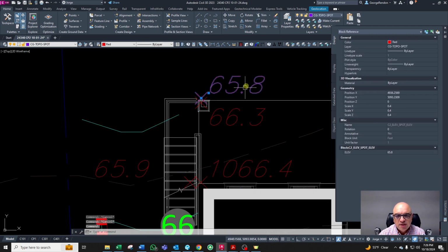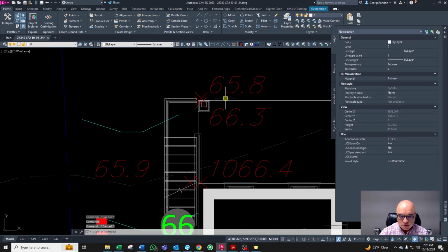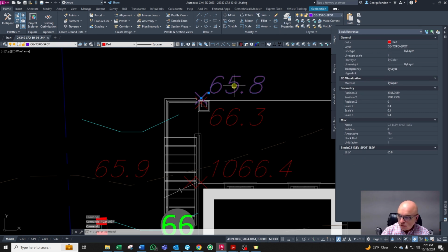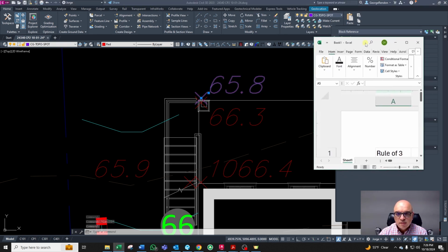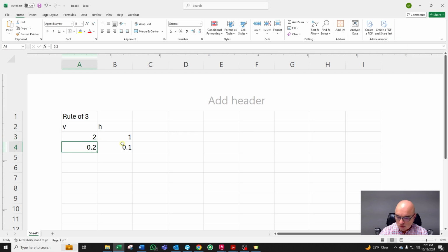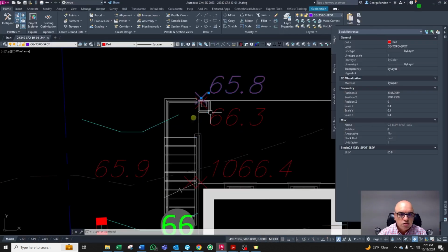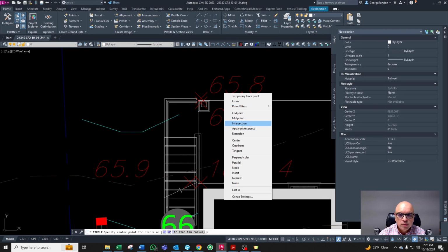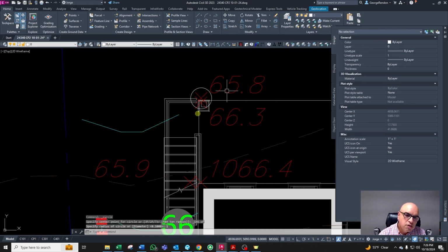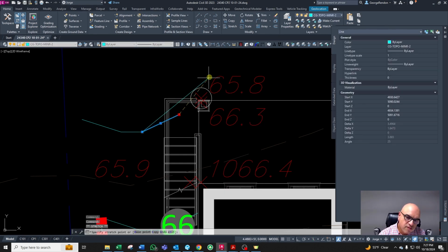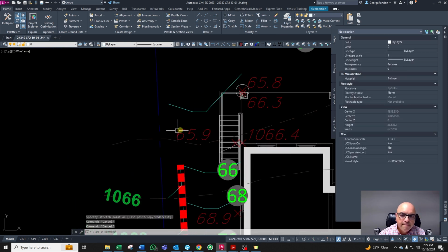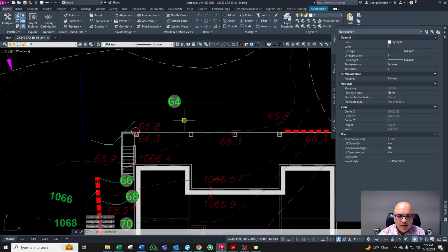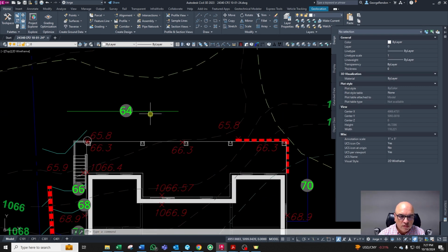But then we can be 2 to 1 on this corner. So we're talking about 1.8 feet to be at 64. So 1.8 at 2 to 1 is going to be 0.1. So we need to be 1 foot from this corner. So my 64 is actually doing something like this. We can do it like that. And I wanna have like a flat area right in front of here for guests when they come out of the patio. They have like a little section they can walk before they start going downhill.